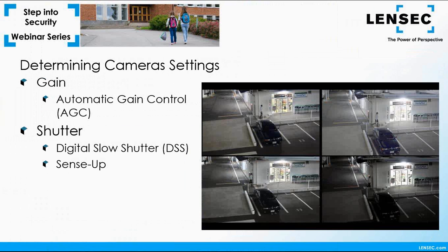Shutter speed also affects your image. The shutter speed indicates how fast the shutter opens and closes in a second. If your camera shutter speed is set to 1/20th of a second, then you won't be able to achieve more than 20 frames per second, even if your recorder is set for a higher frame rate. The longer the shutter stays open, the more light gets to the camera imager. However, lengthy shutter speeds mean that movement, in particular fast movement, might be blurred in the captured image. A faster shutter speed will stop the action better, but more light will be required on the scene.